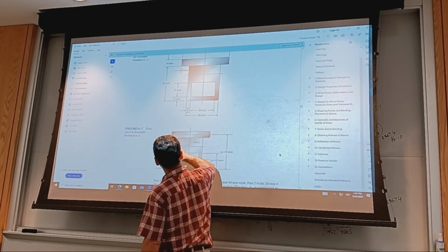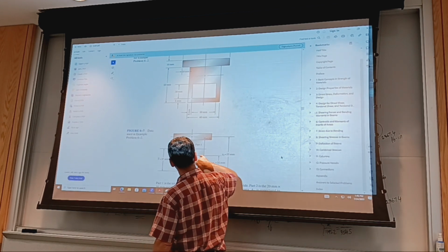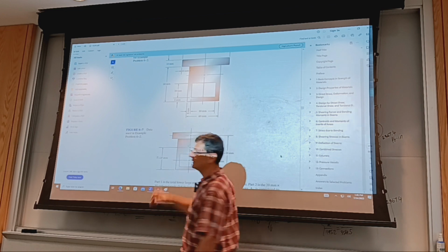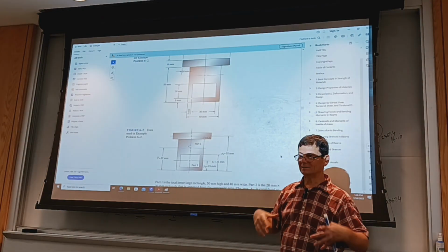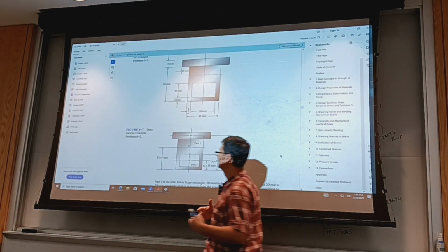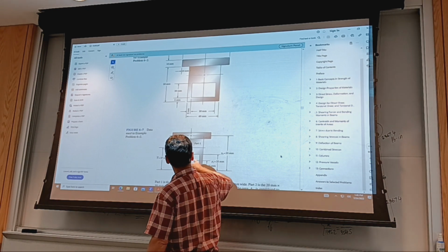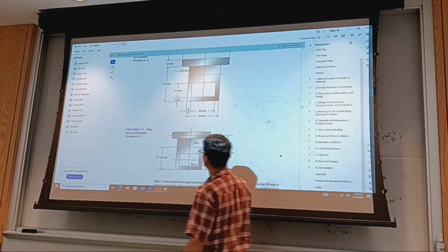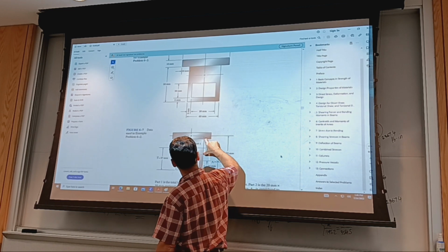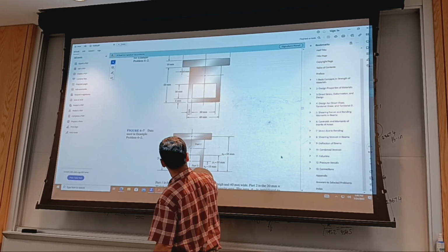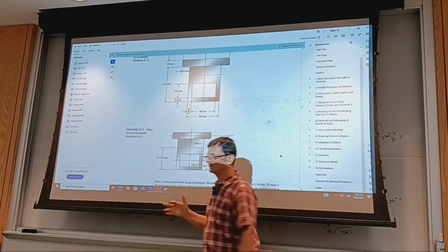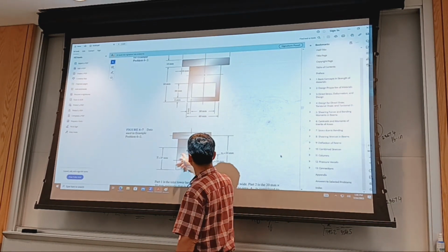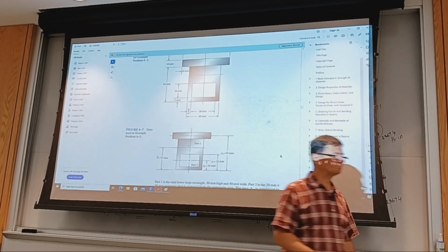Then I can take this missing part, where it says part 2, as a negative area. And then part 1 is going to be one big rectangle. The alternative is to take only positive areas: 1 and 2 and 3 and 4. It's easier to go with a negative area like it's shown here.